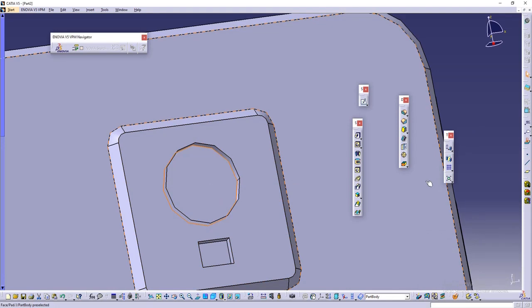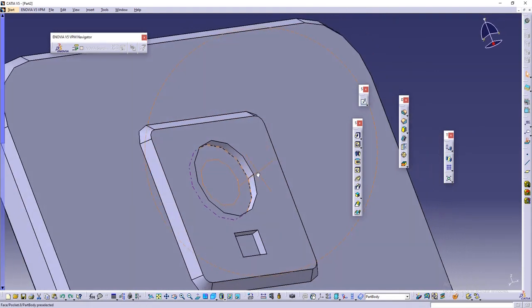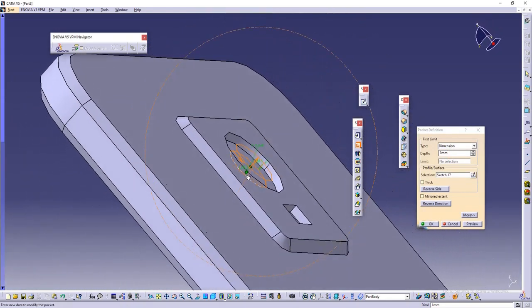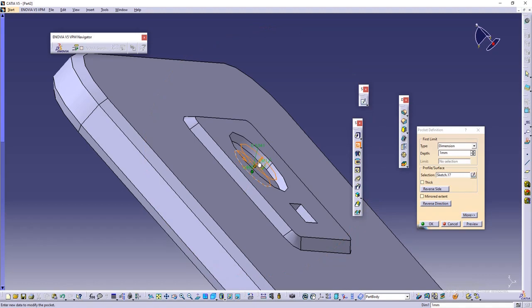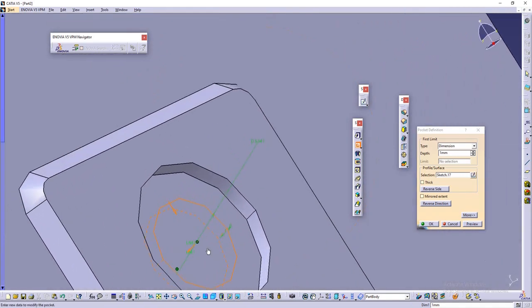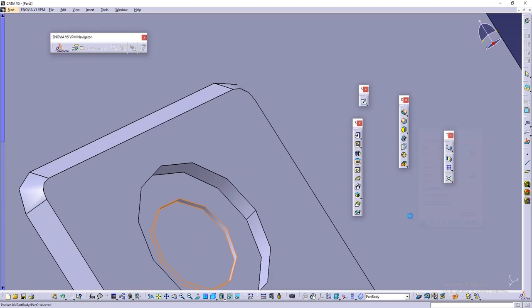Okay, so now I created the pad, but my dimensions are not better. This problem may happen a lot of times because we created the surface and see it is outside, so maybe you have to create it inside, right? So again I need not 1, now I need maybe 0.3 will do.